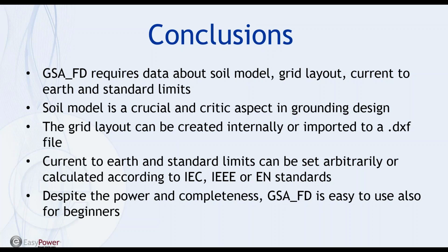We saw GSA FD requires data about the soil model, the grid layout, the current to earth, and the standard limits. As understandable, soil modeling is a crucial aspect in grounding design. The US and Canadian markets in this regard are very demanding, and for this reason XGSLab has been equipped with a powerful soil resistivity analyzer based on the trust region method, a calculation method robust also in case of ill-conditioned problems.